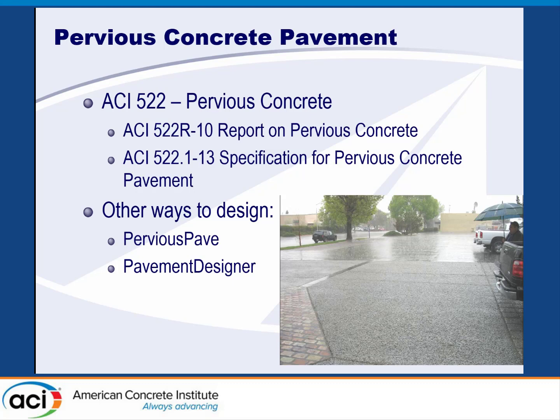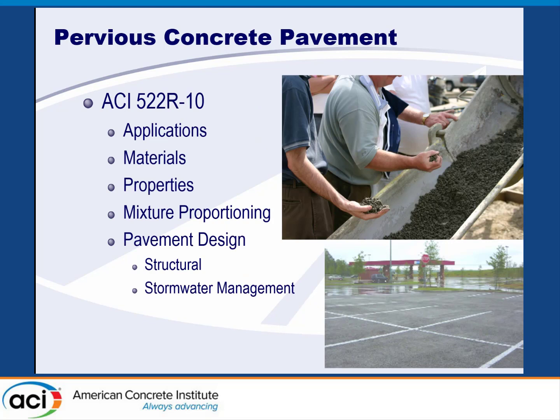We can also use the structural design in Pavement Designer as well. And so 522R10 goes through the applications, again very similar to what we've been talking about: our streets and local roads, parking facilities, and it goes through the material properties and mixture proportioning. You can see here, it's again very different from our conventional concrete because we have low fines, trying to create a void structure, move moisture, and still carry a load. And so it goes through how we do that.